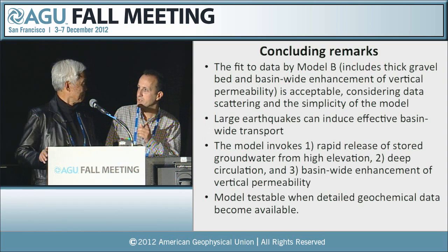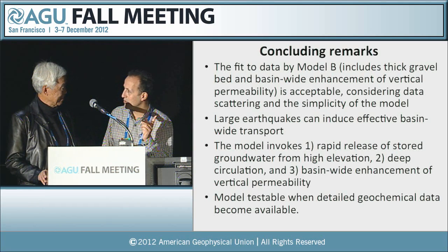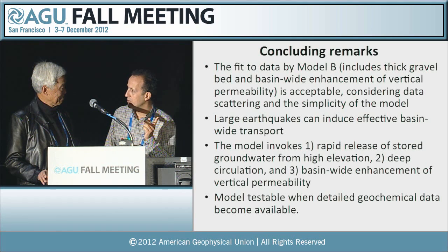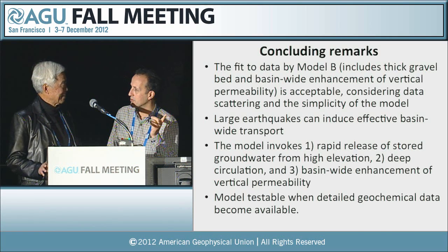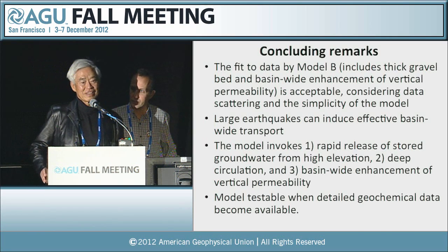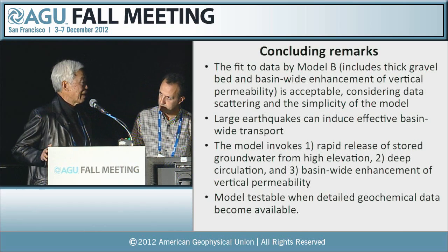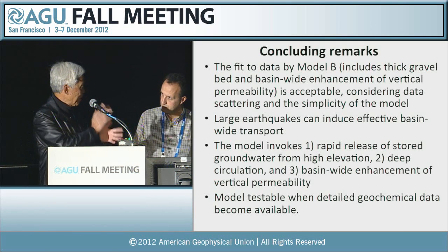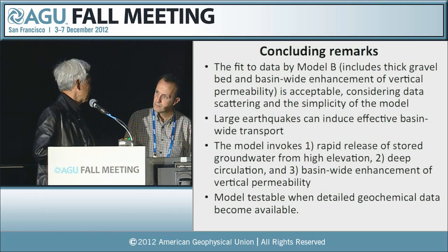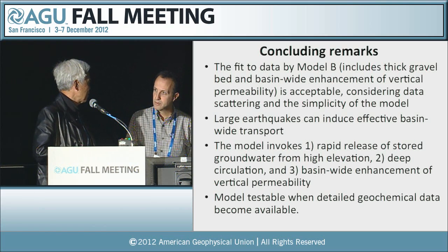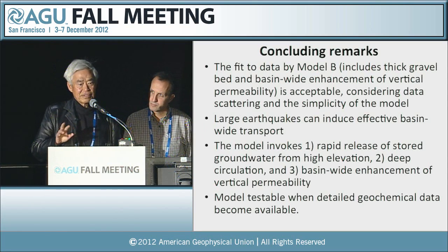I have a follow-up question on that. Do you also change the storativity due to the earthquake? Because if you change the permeability, you change the porosity, therefore you change the storativity. Yes, that's a very good question. The permeability change we assumed, and that is supported by field evidence, is a result of the creation of thin subvertical cracks, which has very little storage by itself in comparison to the storage of the gravel. So we didn't change the storage before and after the earthquake.